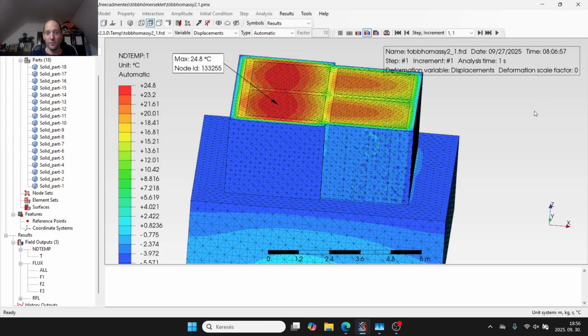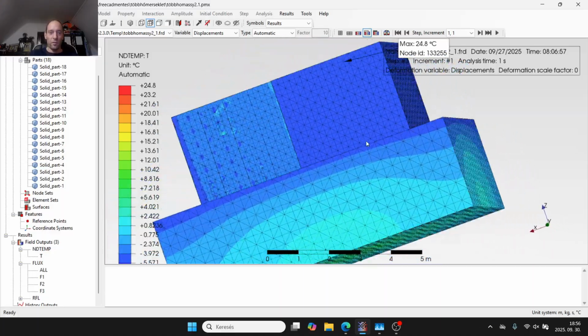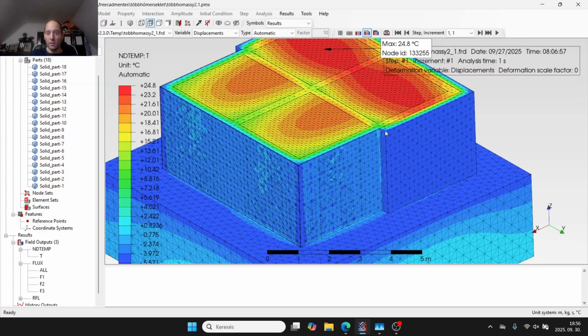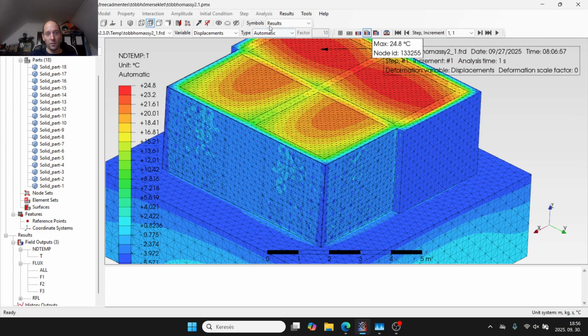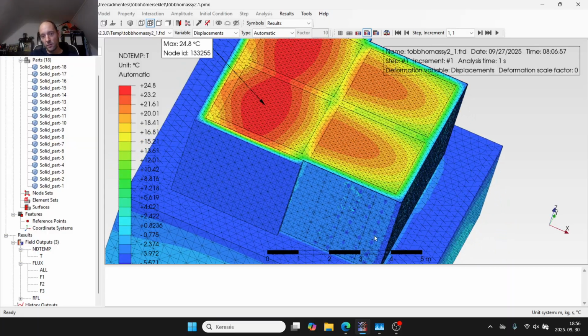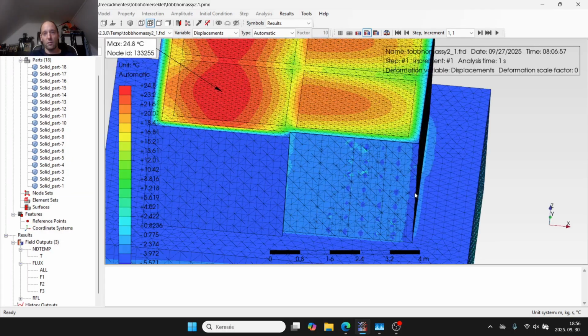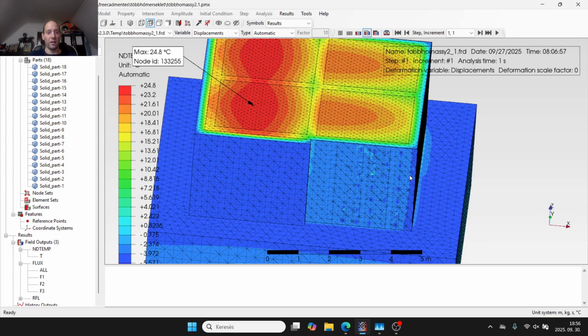Let's see what we have. So here you can see a building without roof. Actually the walls and half of the building is isolated with 30 centimeter thick EPS isolation. The other side is not isolated, as you can see, and the wall is 30 centimeter thick, and the typical Hungarian brick is the material, the B30. It's a burnt clay brick.